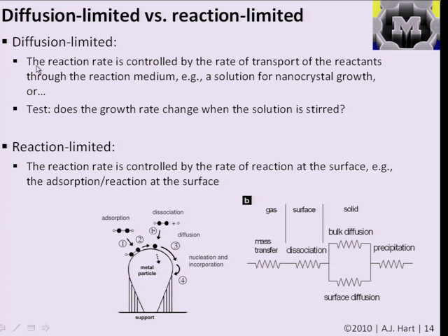But in other cases, we could consider that there may be many more steps. For example, if you have a gas phase process or a liquid phase process that involves, say, first a dissociation of a molecule and then a transport of a molecule and then some addition to the surface, and maybe once it adds to the surface it diffuses and it might react with something else and desorb and so on, there are a lot of cases where the processes are much more complex. And things like the diagram I showed briefly last time, where you might have multiple limiting steps, and you may have to analyze the process to understand what step is actually limiting.